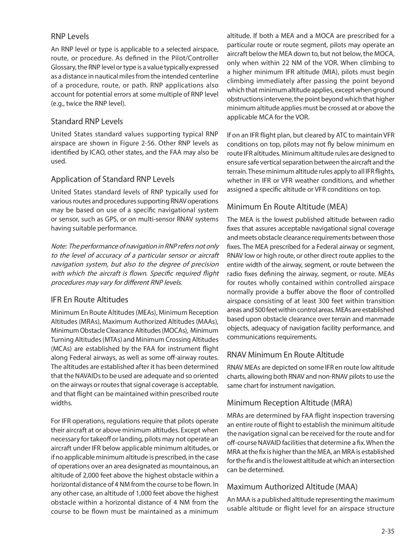IFR en route altitudes. Minimum en route altitudes, MEAs, minimum reception altitudes, MRAs, maximum authorized altitudes, MAAs, minimum obstruction clearance altitudes, MOCAs, minimum turning altitudes, MTAs, and minimum crossing altitudes, MCAs, are established by the FAA for instrument flight along federal airways, as well as some off-airway routes. The altitudes are established after it has been determined that the NAVAIDs to be used are adequate and so oriented on the airways or routes that signal coverage is acceptable, and that flight can be maintained within prescribed route widths.